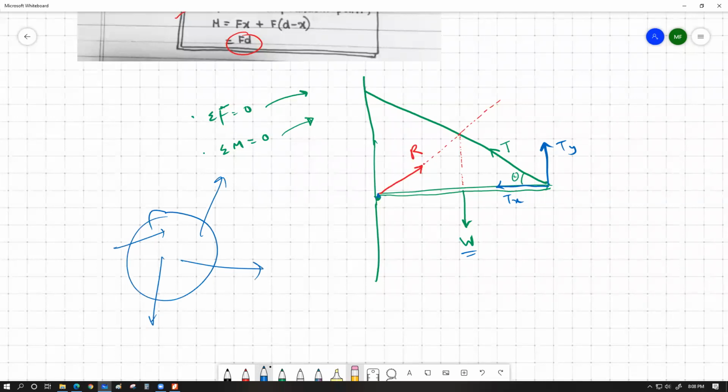For example, in this case, we are trying to find the equilibrium condition for the plank, and the cross point for all the forces falling on the string right over here. It is not within the plank. That can also very well happen. So that's how we define the direction of the reaction force.